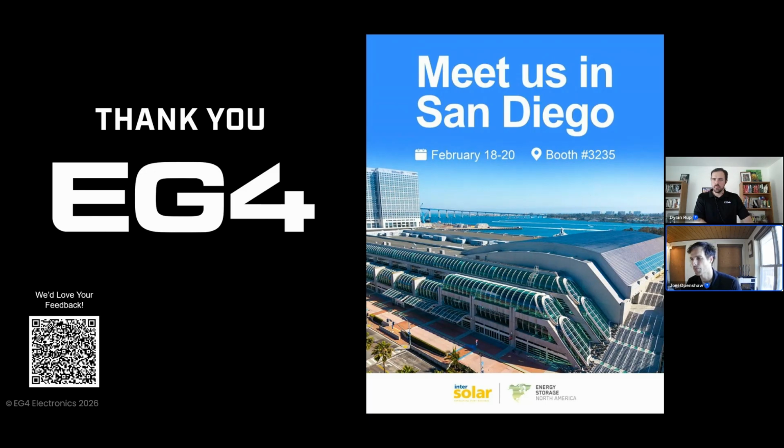In a situation where you don't want to be blowing up transformers or equipment in the home, maybe fancy TVs or stereo systems, that would be a great case to use a chargeverter, where you can take dirty, unreliable power, some with a total harmonic distortion well beyond our limits, clean that into DC power, and then make sure all of the power in the home is going to come from our EG4 inverters.